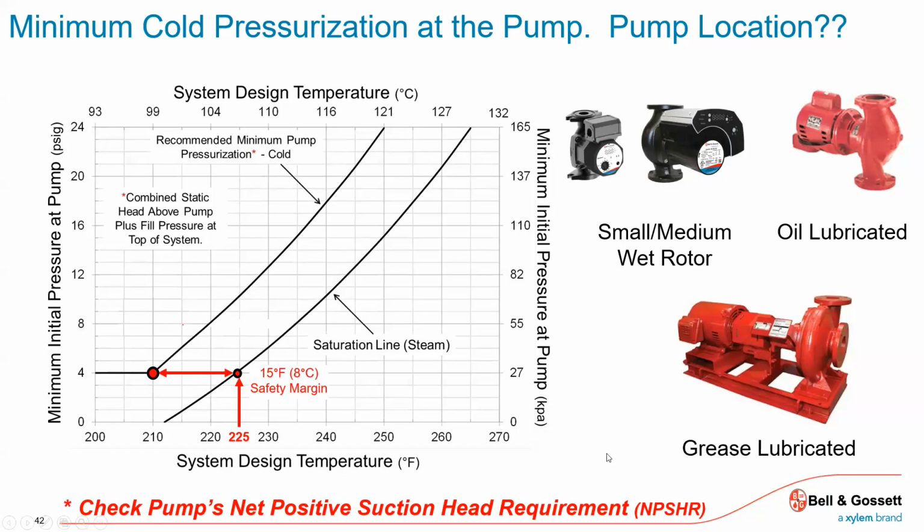That's a positive. The only time this gets really important is when sometimes they'll have the mechanical room up in the penthouse. That's the highest point. So all the weight of the water is down below, but it's not helping my pumps up in the mechanical room. If I'm dealing with really hot water in that mechanical room, I'm going to start paying attention to my fill pressure. How do I set it? Because it's really not about filling the building, since if I get water at the high point, I've got it at the low point. It's all about potentially protecting the pumps if I start getting into higher operating water temperatures, which is not that common anymore. Typically we're going lower temperature as a general theme, but it's just something to be aware of.